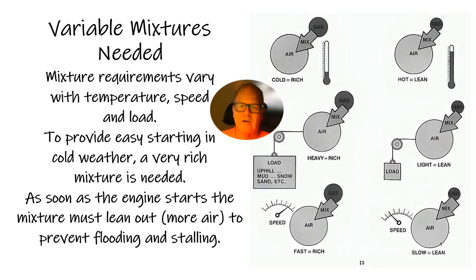Mixture requirements vary with temperature and speed. You've got easy starting in cold weather. You need a rich mixture. As soon as the engine starts, it's got to lean out to prevent it from flooding and stalling. When an engine's flooded, it wets the spark plugs, and the spark runs on that wet gasoline and never jumps across the gap, so it won't start if the plugs are soaked with gas, right? That's why when you mash the pedal all the way to the floor and put it in clear flood mode, it quits pumping gas in there, and that air coming in tends to dry those plugs off, and a lot of times you get one to start up that way.